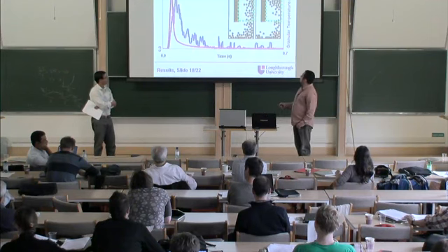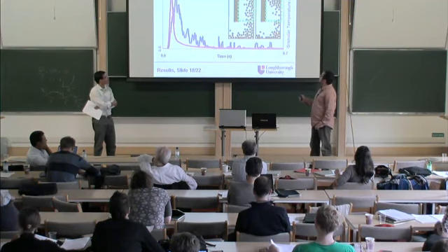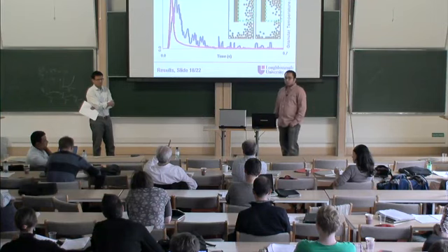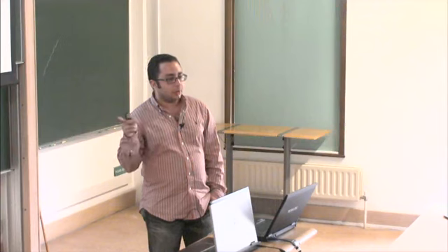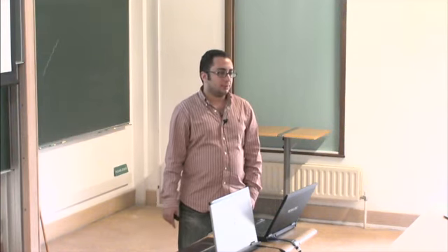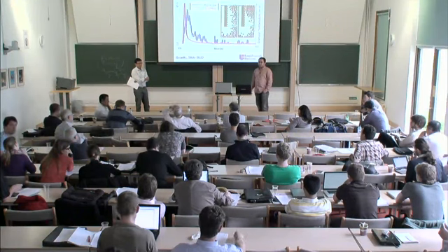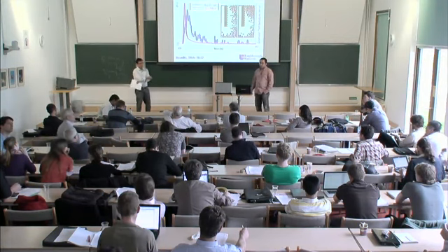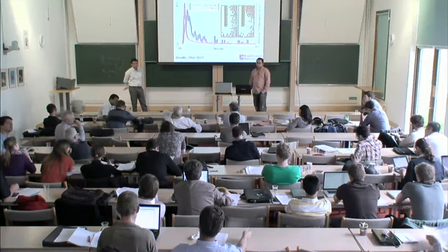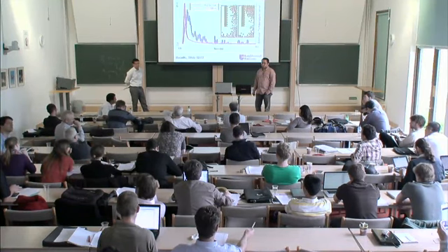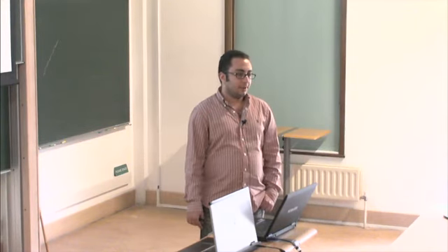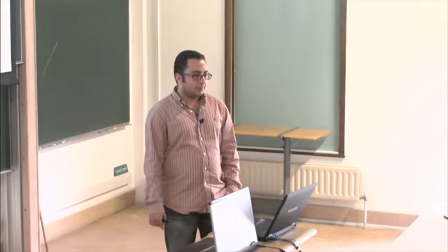Yeah, well, the mean velocity which was computed was just this for the whole particle. In other words, you got one number there for the mean velocity. No, we have it for the x direction and the y direction. So okay, you have two numbers. Yeah, and then the fluctuations for all the particles around this. So the granular temperature then was the instantaneous particle velocity minus one of those two numbers. Yeah, summation over all the particles. Okay. I would suspect that that is the complete source of your discrepancy.